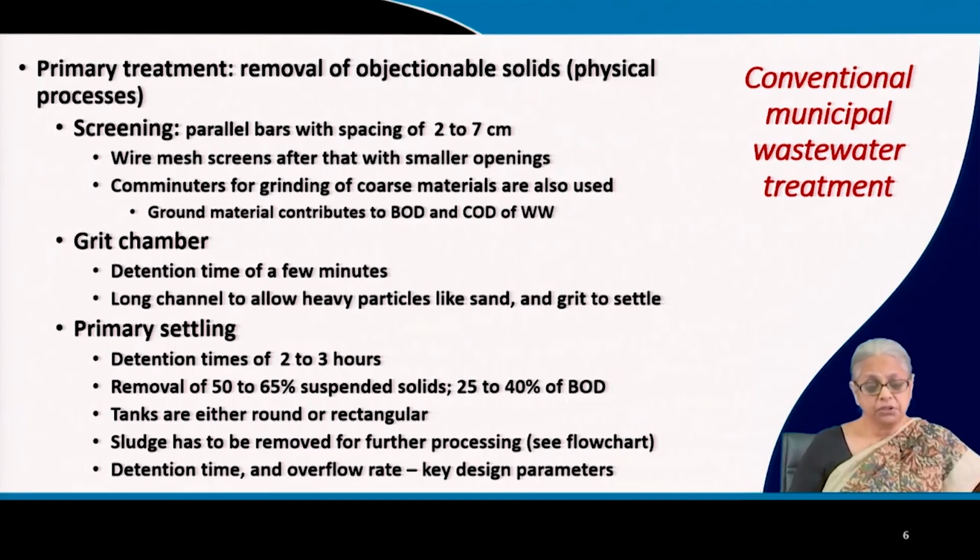We also have a grit chamber. This grit chamber has a detention time of a few minutes. It's a long channel that will allow discrete, which means heavy particles like sand and grit, to settle by gravity.